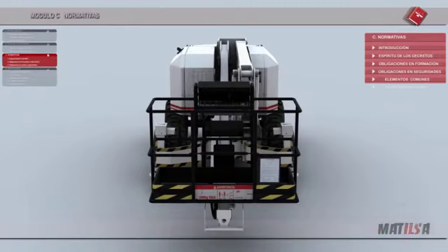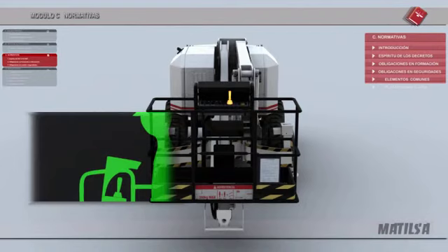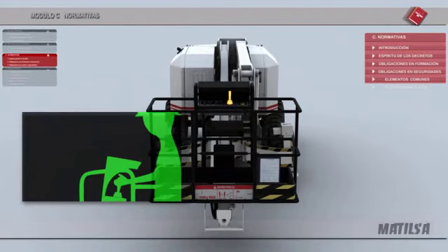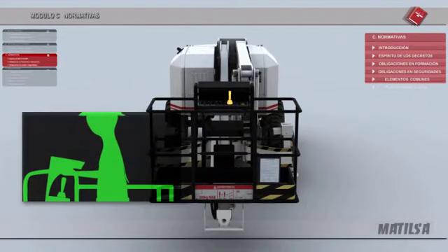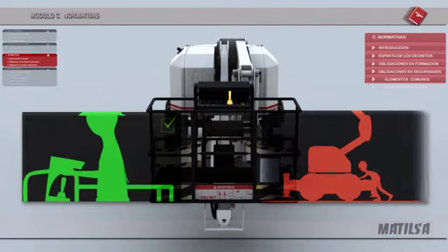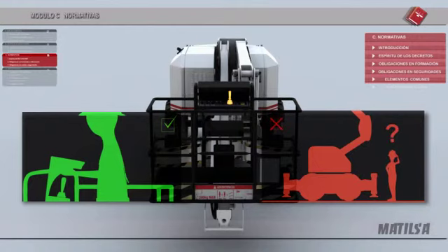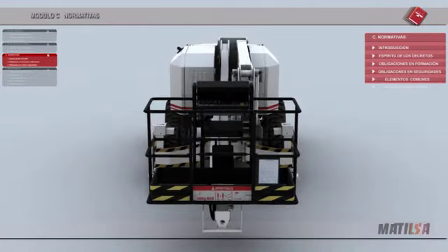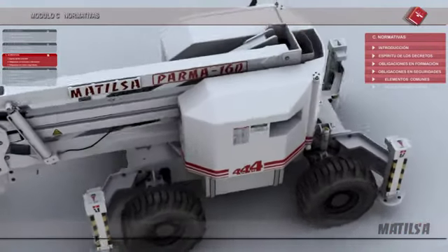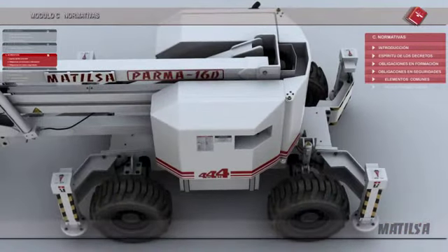Automatic brakes. Their function is to brake the platform as soon as the transporting control of the machine ceases to be used. If the machine is broken down or has run out of fuel and we wish to move it, we must first unlock the brakes. Unblocking braking device for self-propelled machines in general.